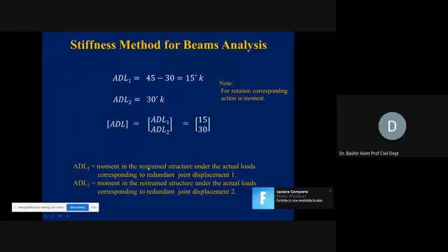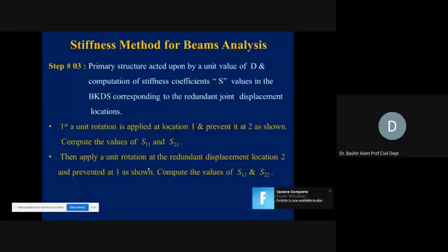So you should not be having any problem now when you go to the next problems in generation of the AD matrix as well as ADL matrix also. Now stiffness method, the stiffness matrix we will generate. So in stiffness matrix now, this is parallel to when we were generating the flexibility coefficient matrix in the flexibility method.